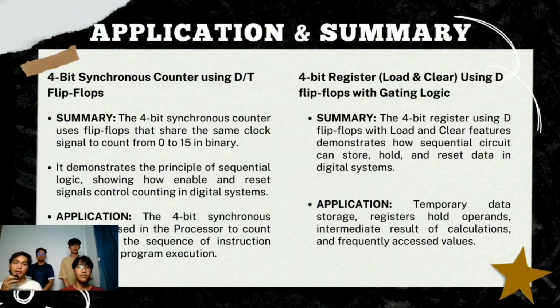Okay, so next, application and summary for the 4-bit synchronous counter using D or T flip-flops. For the summary, the 4-bit synchronous counter uses flip-flops that share the same clock signal to count from 0 to 15 in binary. It demonstrates the principle of sequential logic, showing how enable and reset signals control counting in a digital system. And for the application, the 4-bit synchronous counter is used in the processor to count and control the sequence of instruction steps during program execution.